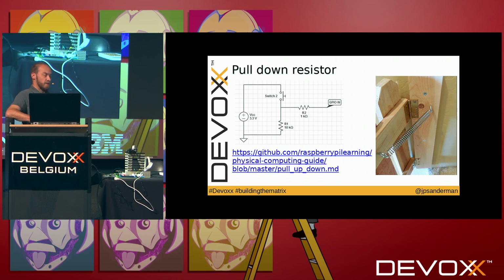On the website I mentioned here, there's a great explanation of how a pull-down resistor works. And it compares it with a gate. And the gate can open and close very easily, even with a gentle breeze. And you don't know if the gate is open or closed, as it is constantly switching between these two positions. Now, if you would add a spring to the gate, you could keep it closed. And you would need a deliberate push to open it. Now, the gate's position represents the voltage, which is constantly fluctuating. And the spring represents the resistor, which you can use to fix the voltage to either high or low.